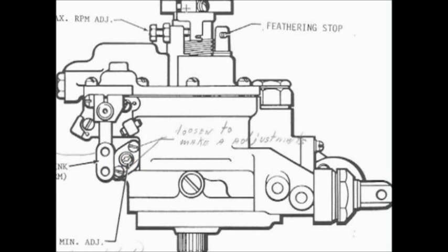One thing I would do, instead of disconnecting the rod end, when you change prop governors or fuel controls or any other item that has a rod end and a push-pull control on it, is leave your levers attached to the rod end and pull your lever off your control rather than detach your rod end and your control.